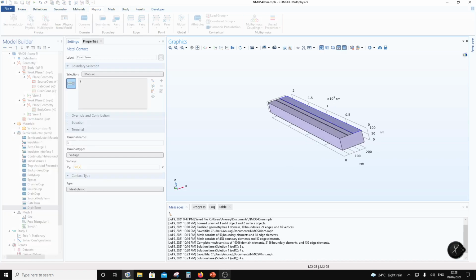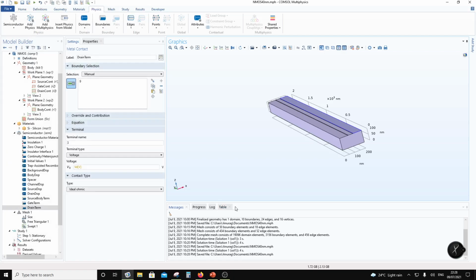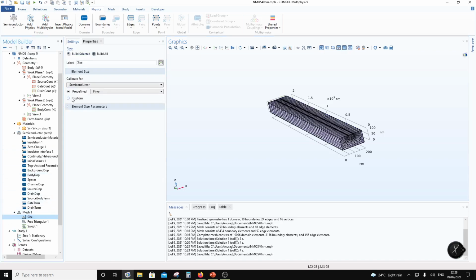Now the next important thing is, in case of Laplacian solvers, in case of method of moments, in case of FDTD, maybe in FDTD you might struggle with the stability. In case of FEM or MOM, you will never struggle with convergence issues. But here, convergence is a very big issue. In COMSOL, it might not converge if you do not do it properly. So mesh settings you might have to play around with a little bit.